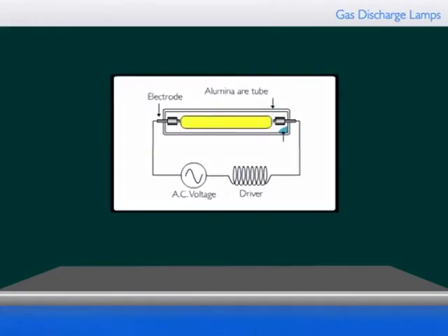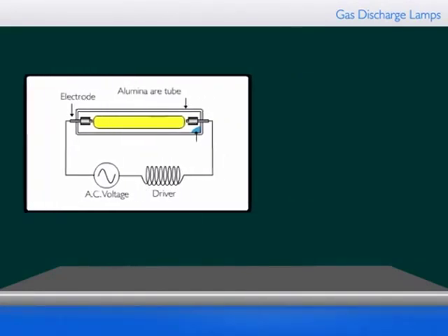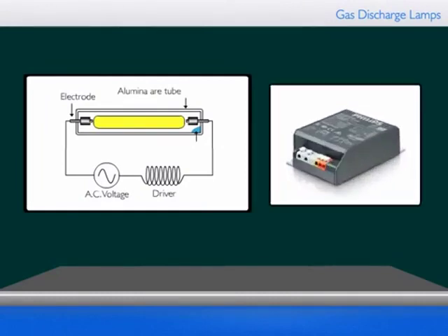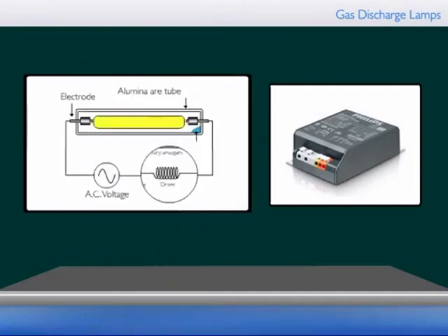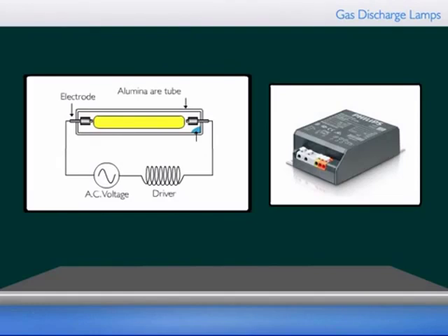Gas discharge lamps do not work by simply connecting them directly on a main circuit. Operating a gas discharge lamp is only possible in combination with a control gear. Modern control gear has integrated functions that ignite the lamp and limits the amount of current in the electricity circuit by means of a driver. Without the driver, the power of the discharge continues to build up like an uncontrolled avalanche.